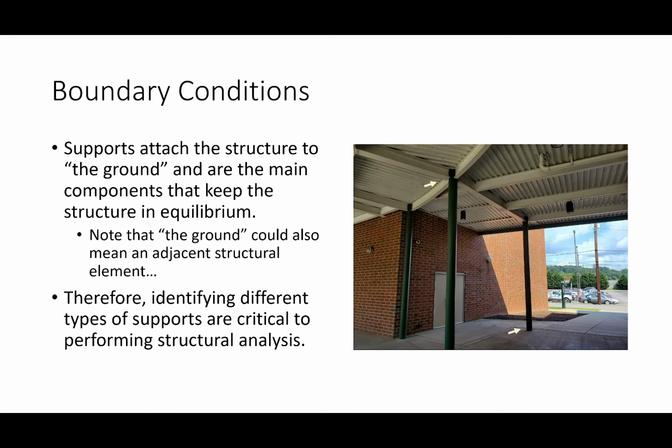Now, would it also make sense, instead of me being in the middle, what if I were to scooch over here a little bit? This leg is going to have to hold up more than this leg, right? Make sense? So what we are trying to figure out is, what are those forces that are necessary to keep me in equilibrium? And so when we say support reactions, I apply an action to a system, the system responds with a reaction, right? That's why we call them reaction forces. Now, the number of reaction forces and how we assign those reaction forces is a function of what boundary conditions exist for the problem.